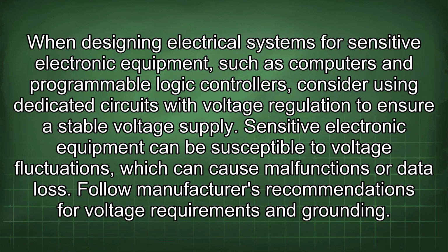When designing electrical systems for sensitive electronic equipment, such as computers and programmable logic controllers, consider using dedicated circuits with voltage regulation to ensure a stable voltage supply. Sensitive electronic equipment can be susceptible to voltage fluctuations, which can cause malfunctions or data loss. Follow manufacturers' recommendations for voltage requirements and grounding.